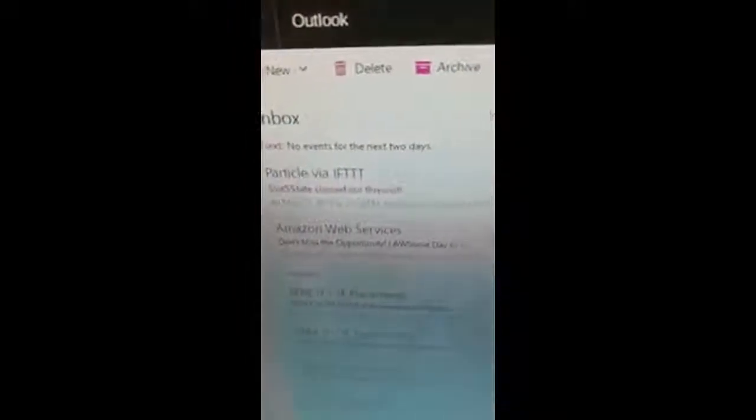the Particle Photon website, when the data is coming through, as you can see, the slot states are coming, and slot number 5 has now become 1. If I go to the email, you will find an email has been received for slot number 5, and if we read it, it says MZ Photon reports that slot number 5 is now 1. I hope this demonstrates the practical use of IFTTT. Thank you.